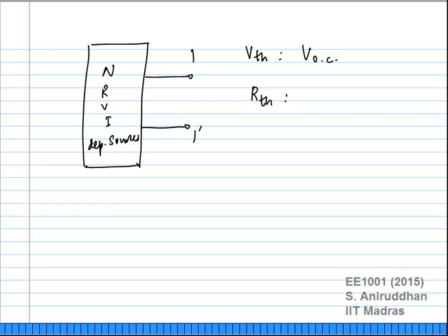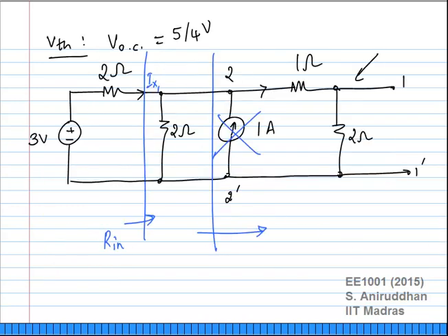Suppose you have a network of resistors and you can take this case. Suppose I null 3 volts and 1 ampere. What will happen to the voltages and currents through these resistors? They'll go to 0, right? If I had some control, let's say I had a voltage controlled current source, and the voltage was the voltage across one of these resistors, what will happen to those sources? The current source will become 0 and look like it becomes an open circuit. But is that right?